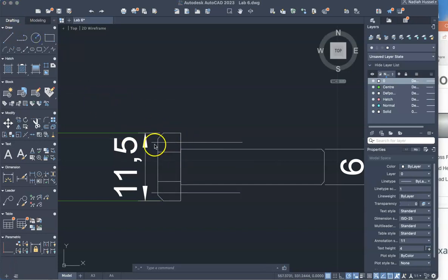Arc. So what I'm doing here is I made a line that intersects this midpoint. As you can see here, if I make a line, it is intersecting the midpoint between here and here. This line all the way from here to here, and I found the midpoint. Same case over here, or you can just mirror it. Now why I need this midpoint is because I want to try the 3-point arc.